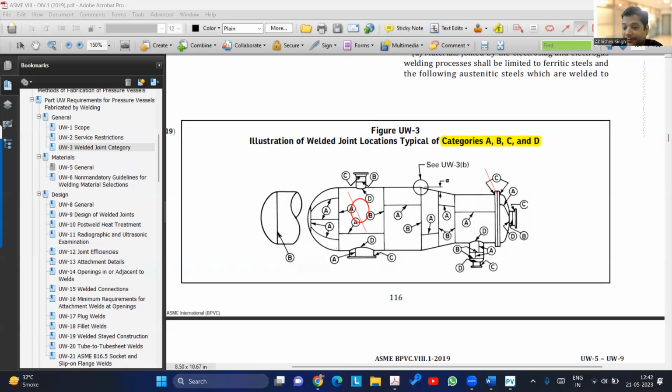Okay, for post-weld treatment, if it is coming, then it is the same, no? Why would it be different? Maybe impact might be one case, but even for impact, the type of welding will have influence. Even for PWHT also, type of welding, but here we are talking about full penetration and butt welds. So if it's a butt weld, then there is no difference. If it's a different type of weld like groove and fillet, then we can find the governing thickness based on that, and it will definitely be different than D.